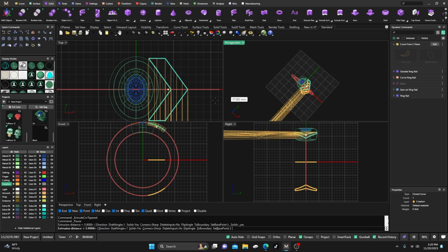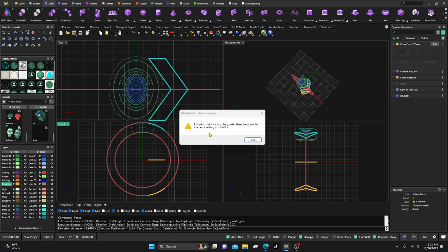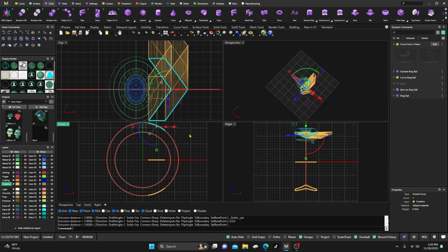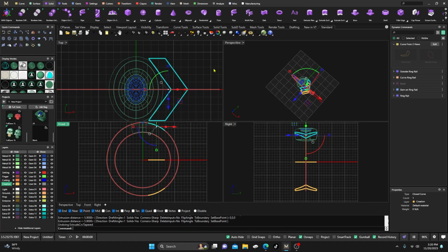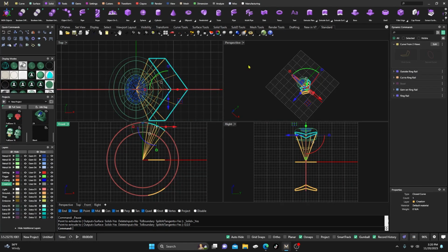tapered, right? And then I'm going to type in F4. Oh, let's taper it. Did I hit straight maybe? Let's get it back out of that one. Let's go to extrude to a point. I'm sorry, to a point, and then hit F4. And it'll snap it right there into our F4.